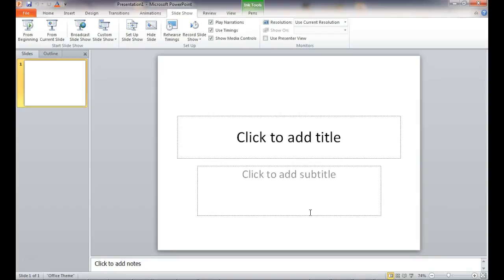And normally what they'll do is they send information in packets. And the packet has a header. Inside that header is just a bunch of zeros and ones. And what happens is when your receiver receives those zeros and ones, what does it do? It allows it to get in sync with the data that it's being sent. And then once it's in sync, then it just reads at a precise time.